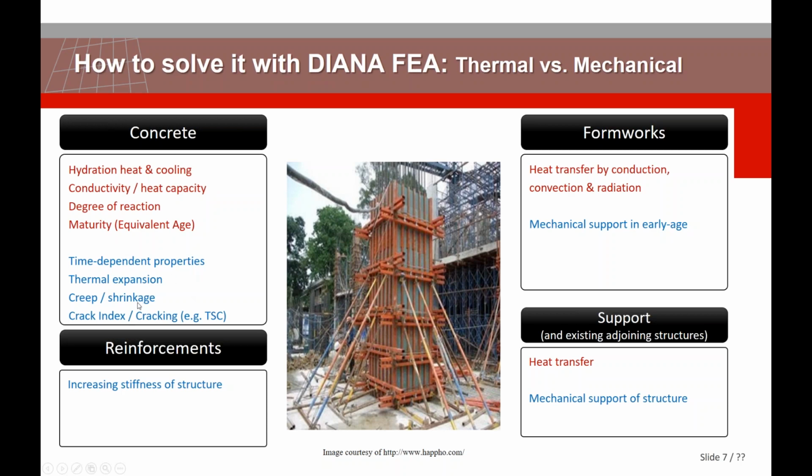In DIANA, you can get a crack index if you run a linear analysis. If you want to go non-linear, you can use the total strain crack-based concrete model, and you will get nice cracking, crack propagation, crack width, and crack spacing. And reinforcement, of course, increases stiffness. This is the mechanical part.